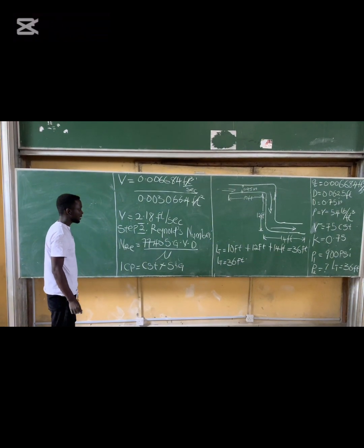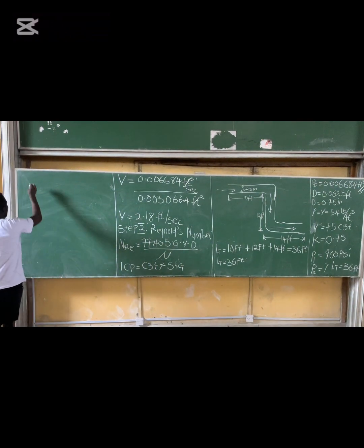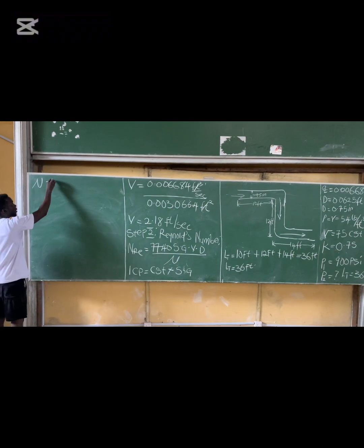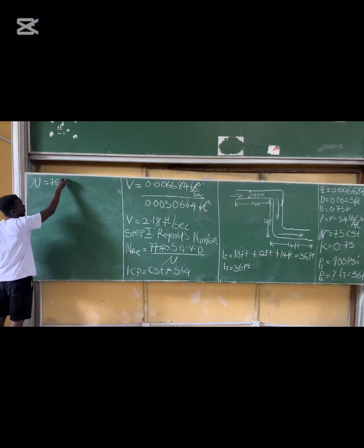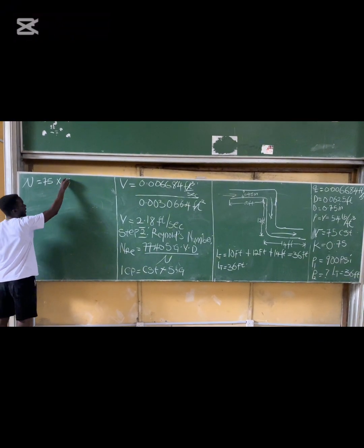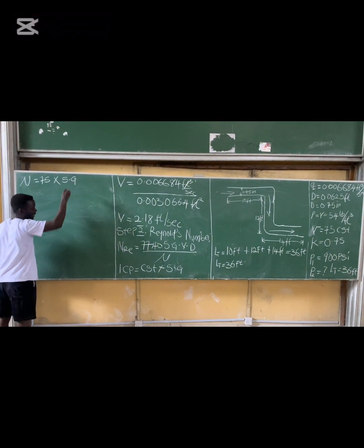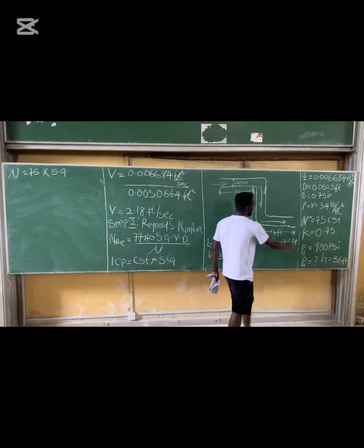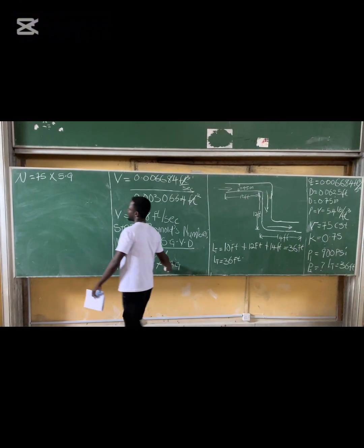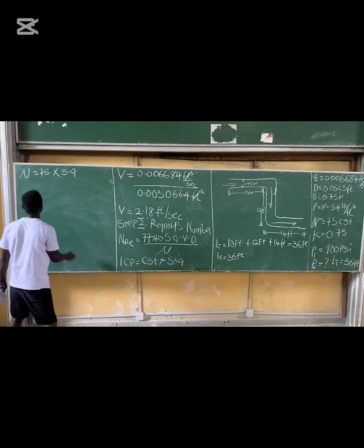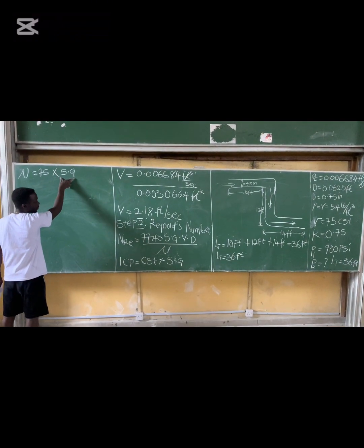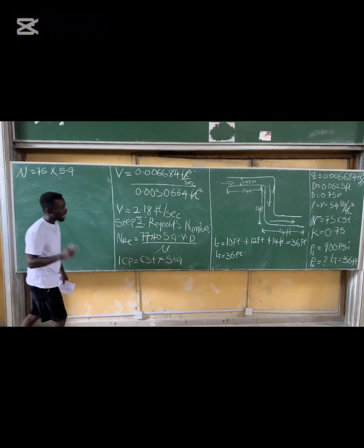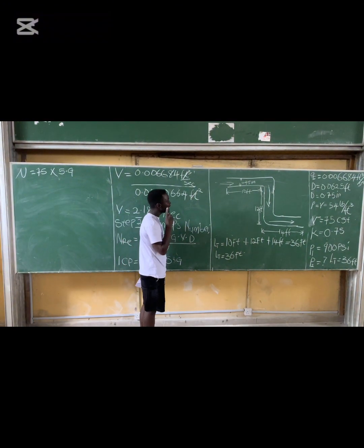specific gravity. In this case now, we can simply say that our mu will be equal to 75 multiplied by the specific gravity. Remember, they gave us the viscosity in centistokes, which is 75, times specific gravity, which is not given. So I can say that our mu is equal to 75 times specific gravity. If we substitute inside the formula, also note that the diameter here is in inch and not in feet.